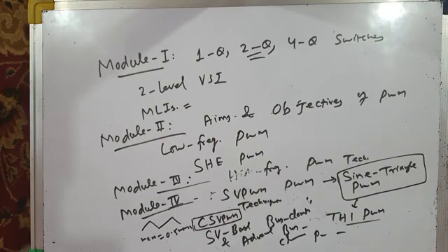So we then discussed space vector based bus clamping and advanced bus clamping techniques. We studied the concept of stator flux ripple, how to reduce the stator flux ripple using conventional space vector PWM technique or space vector based bus clamping techniques and advanced bus clamping techniques, the torque ripple in induction motors, and hybrid PWM techniques which we can use for reduction of torque ripple in induction motor drives. We discussed that in details. Then I discussed with you the effect of inverter blanking time or inverter dead time on inverter output voltage in a couple of lectures.